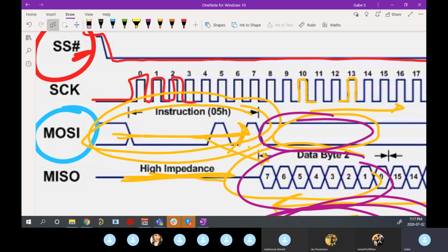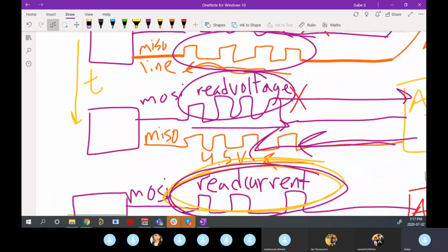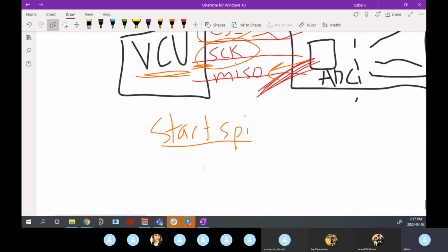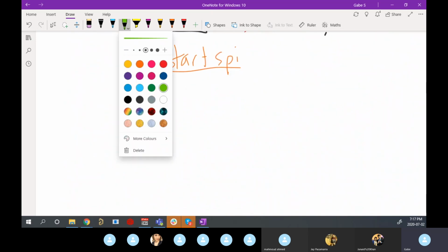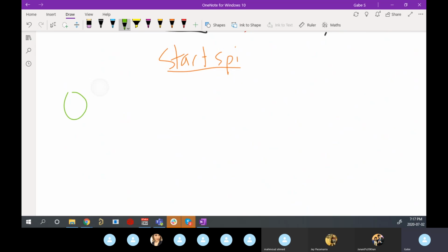that's basically what the value of the data they sent in this specific case is. It could be anything that you're sending. You could send whatever you want. So this instruction is probably something specific to the datasheet of the slave or ADC that says if I get a 05, then I should do X or Y or send Z. But all this H means beside it is that it's hex. So 05 in hex. So 05H. What this H tells you is that you're looking at hexadecimal format.